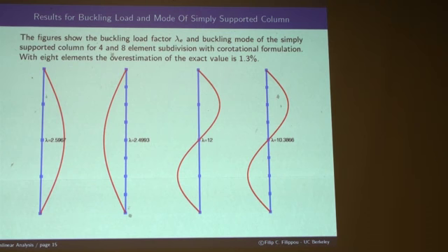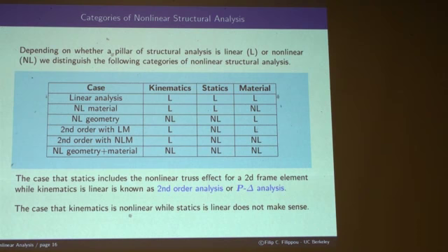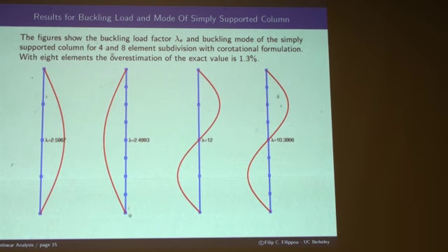So if you want to study the buckling of unbraced frames, you don't need to subdivide the columns because the lateral displacement is the most important effect and the chord captures it, right? If you want to be more precise, of course, you can subdivide it and spend more time. All right, so I tried to illustrate basically how we capture the phenomena of nonlinear geometry.